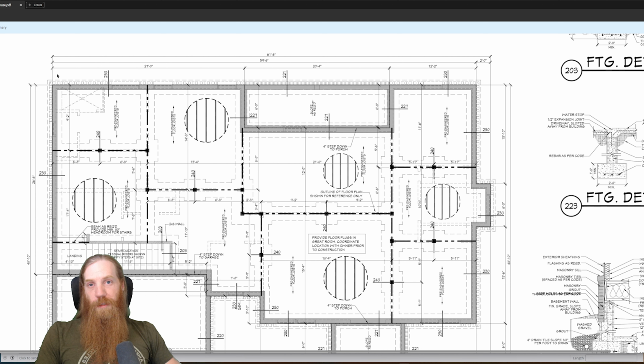If you do have an actual set of plans, then it's very important that you look and see where the measurements are actually going to, because they're going to be exact on their placement. Okay, or they should be. If you have any decent set of plans, all of these markers should be exact, identifying exterior. So in this case, this 61'6", so it's 61.5 feet, is measuring from the exterior of the foundation wall to the exterior of the foundation wall on the opposite side.